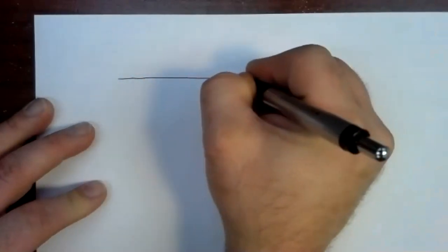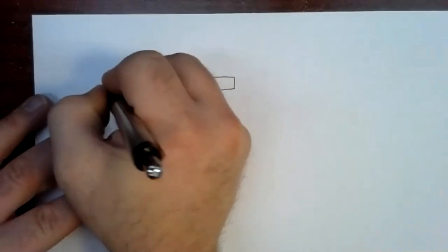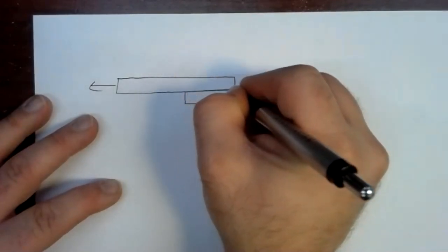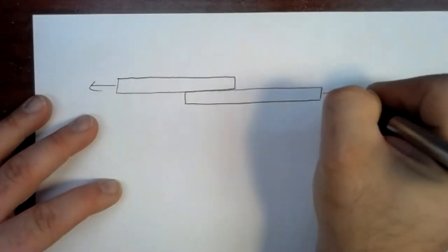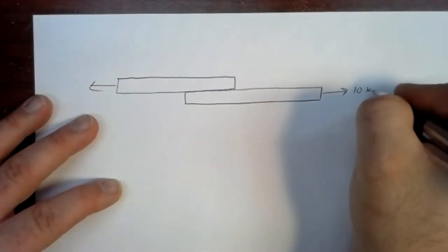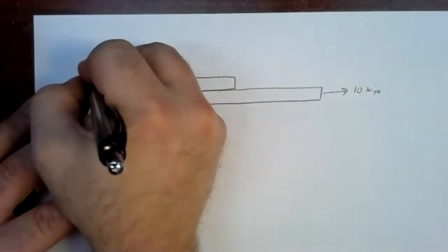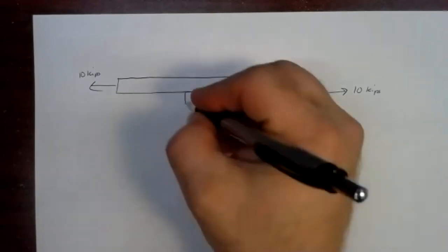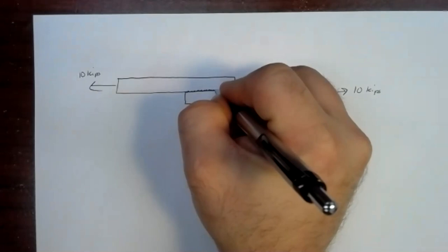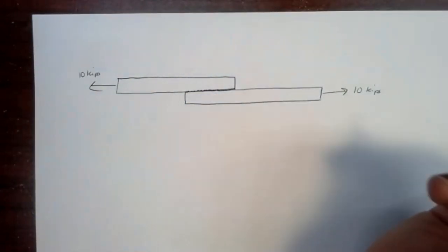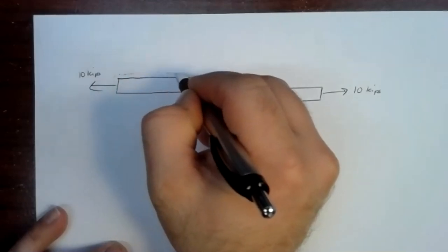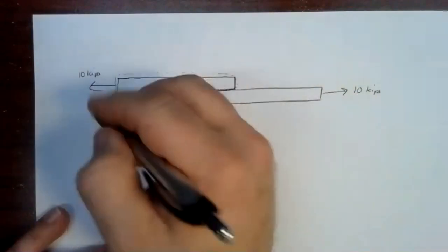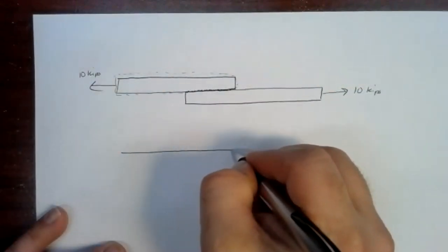So here's the picture we had on the slides. We have two plates glued together in a lap joint. Let's put 10 kips on it. So there we've got 10 kips of force, and this is in equilibrium. There's a layer of glue right here. Well, think method of sections. If I were to draw a little bubble, a system boundary, around just this top plate, the free body diagram of that top plate would look something like this.